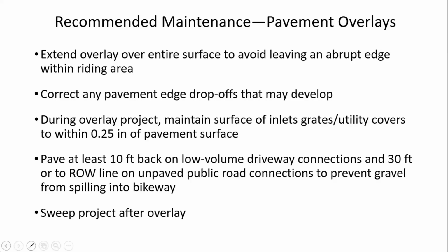As I mentioned before, think about maybe paving back at least 10 feet on lower volume driveway connections, maybe 30 feet or to the right-of-way line on unpaved public road connections to try to reduce the amount of gravel or loose stone that might spill into the bikeway. And then after overlay projects, again, sweep the roadway.